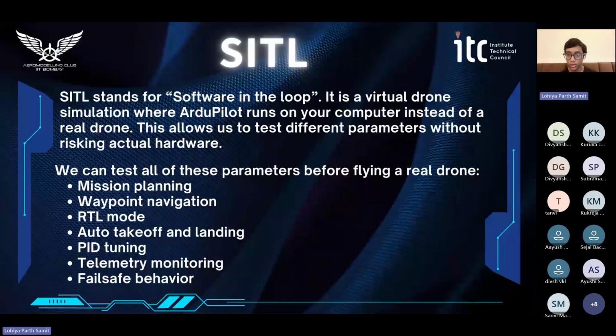Moving on, we have SITL, that is software in the loop. It is a virtual drone simulation where ArduPilot runs on your computer and flies a virtual drone instead of crashing your real drone in case anything goes wrong. And we can use it to test parameters like our mission planning, our waypoint navigation, our RTL mode, our PID tuning, our takeoff and landing, our telemetry monitoring, and also most importantly, the failsafes.